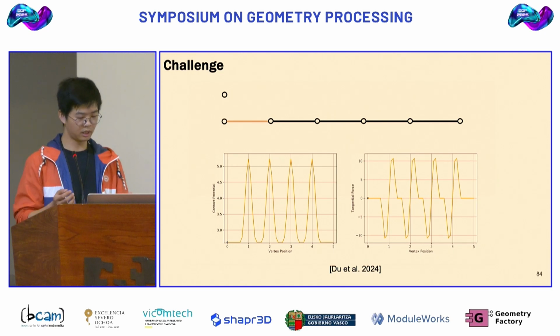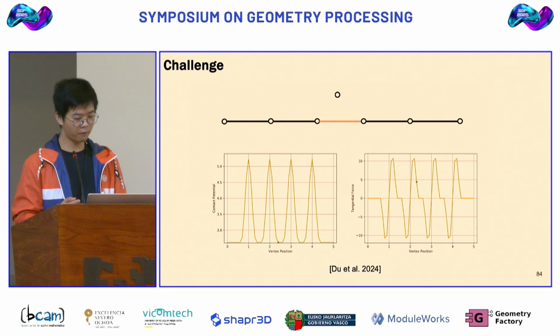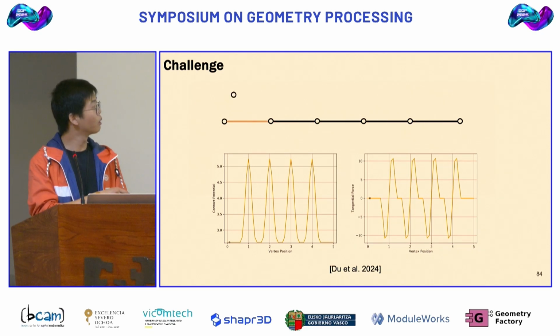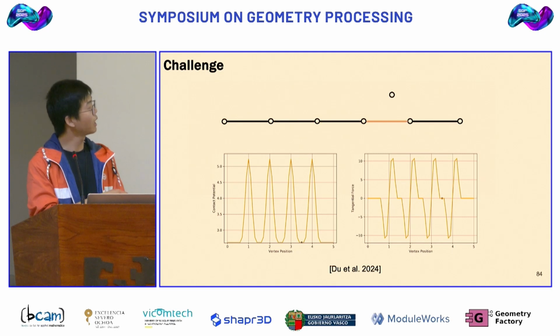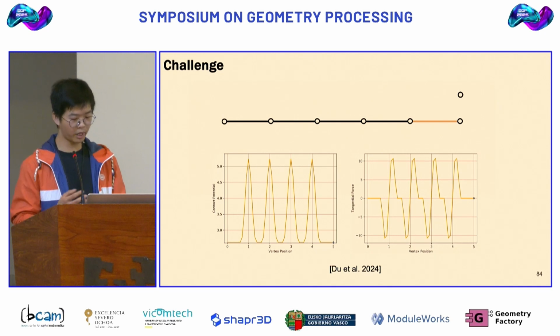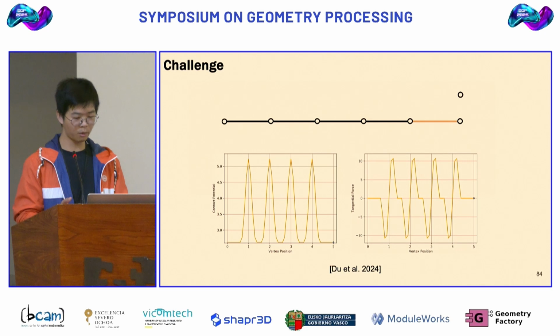Another problem is that in IPC, also called incremental potential contact, the incremental potential relies on a superposition of smoothly clamped contributions from a set of active primitives. Here, the contact potential energy of a vertex with an edge will change from 1 to 2 and 2 to 1, and this will introduce a contact energy peak at the segment junction, as shown in the left side plot. Basically, if a point moves from left to right, it changes from 1 to 2, and so it gives this kind of energy peak. In our case, it will impede the free sliding of the interlocking elements during the optimization, so the problem will slow the convergence of the forward and inverse problems.